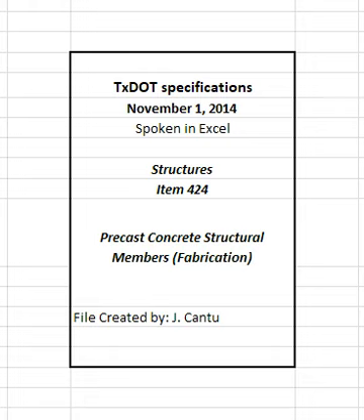When the maximum acceptable placement slump or slump flow is exceeded, the affected concrete will be rejected and retesting for slump or slump flow will not be allowed regardless of the concrete placement times. Additional requirements for precast mass placements will be in accordance with Item 420, Concrete Substructures. In the case of a conflict between the two items, the more stringent requirements apply.